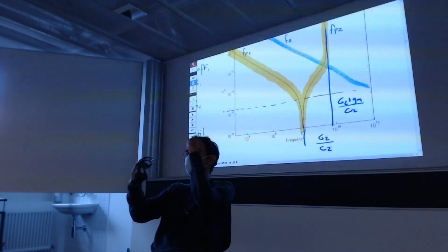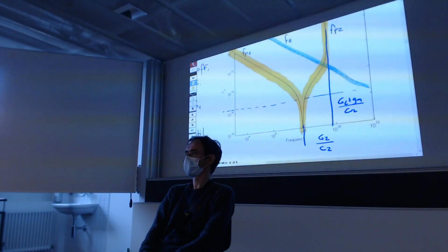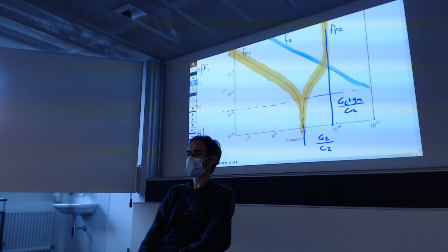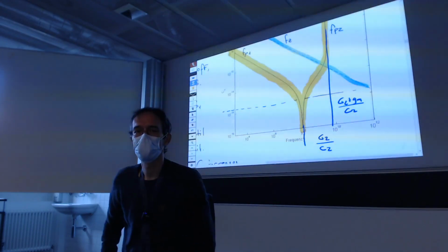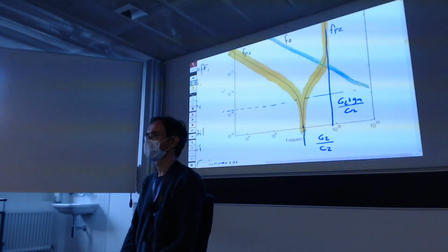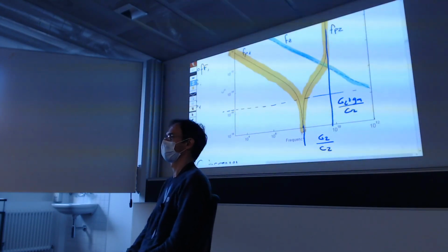Basically, if you do the full feedback, it is like a resistor of the conductance Gm, and that is always there. If you want the output pole to go even higher, you would need more conductance there. But where should it come from? I mean, the Gm is limited; it is not higher than it is, so there cannot be more conductance.